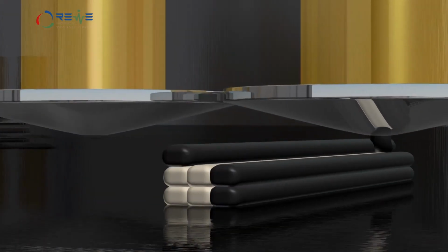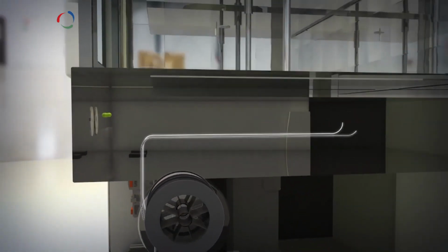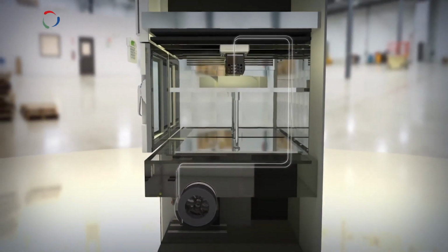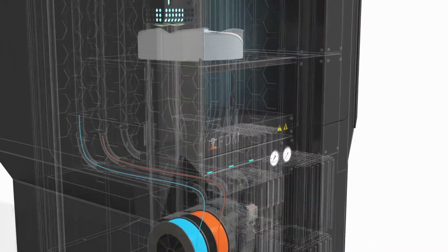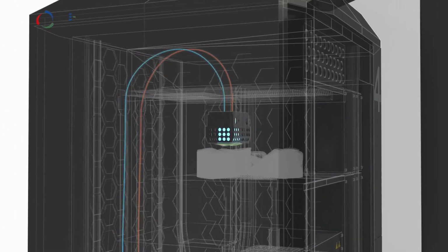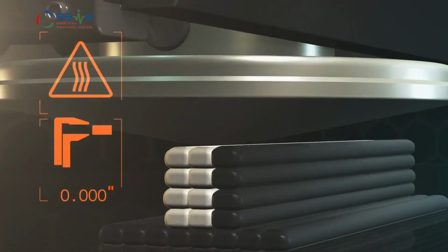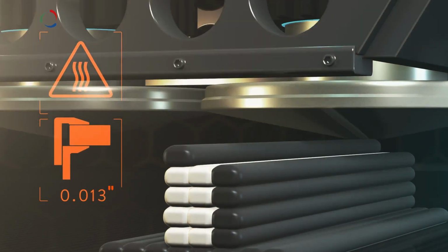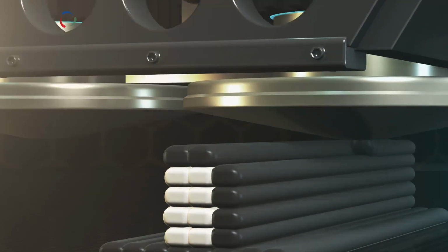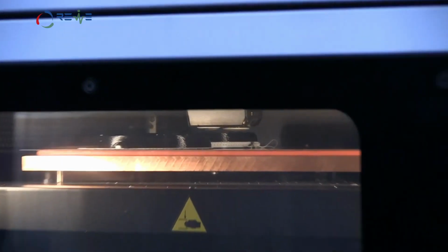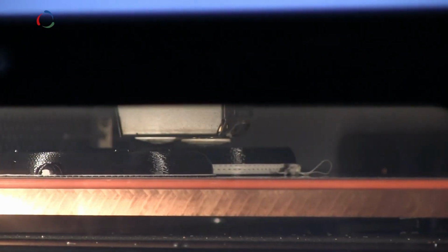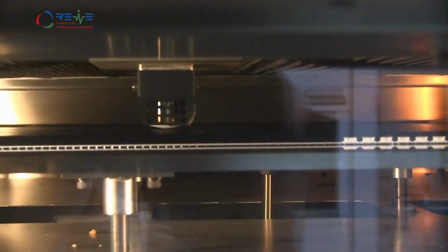The nozzle has a direct feeding system that can either be placed on top of the nozzle, or an external feeder that would feed a filament type material into the nozzle. The nozzle is heated, it heats up the material and extrudes it out. The extruded material is placed in a specific design as per your 3D design, which had been sliced and programmed inside this 3D printer. It will print layer by layer and move up slowly.